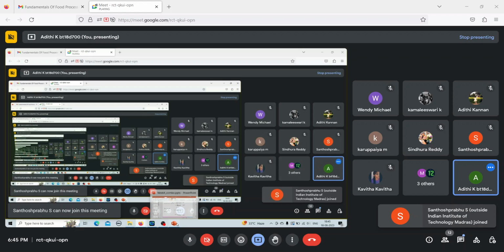From L, we can calculate V from the total mass balance equation. That is F minus L will give you V. So 0.5 minus 0.166 kg per second gives V, which is 0.33 kg per second. Hope this is clear. Always calculate V and L from the mass balance equations if the other parameters are given. S is something that you can always get from the energy balance.